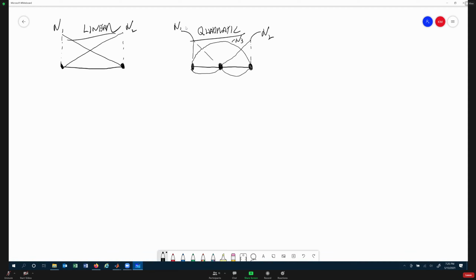So in this linear one, assuming a 1D, where's our integration point? Right in the middle. I think we showed them as X's, right? Do you remember where our integration rule was if we had a single element with 3 nodes? 1 over square root 3 or something. Yeah, it was 1 over root 3 and minus 1 over root 3. So we have two Gaussian points and another node associated with it.